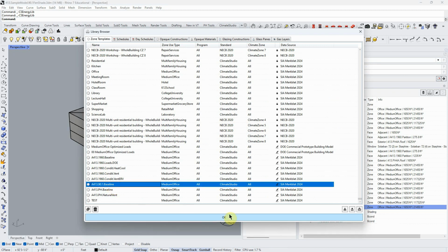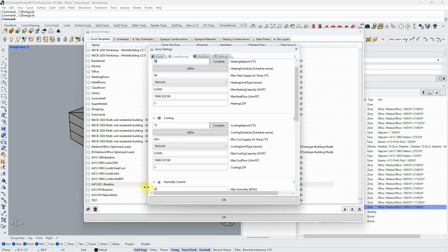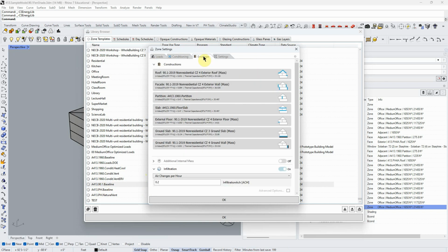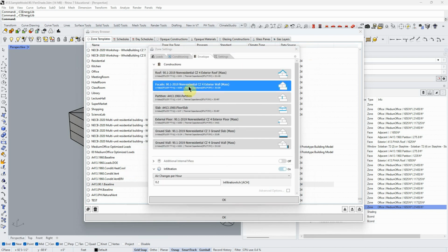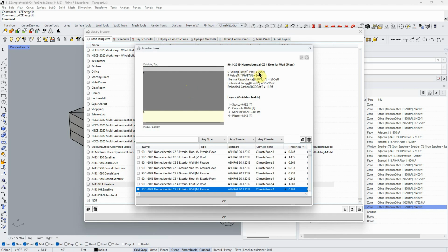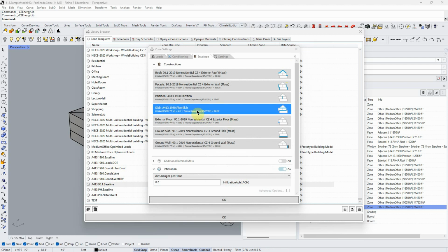So the baseline, and 90.1 is the standard that I talked about. The main things we did is we upgraded. So now we've got an R value of 31 in the roof, which is not extensive, but that's way better than having no insulation at all. Only an R value of 10 in the walls, but with a mass wall that's not terrible because there's less thermal bridging and stuff. It's got thermal capacity. So that's the standard for a decent building these days.